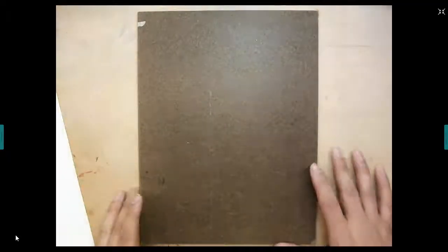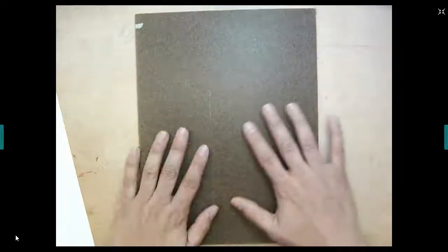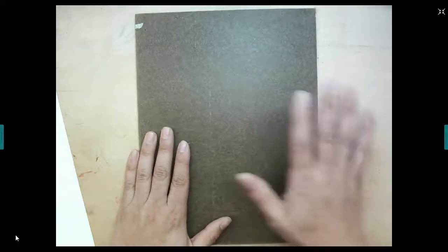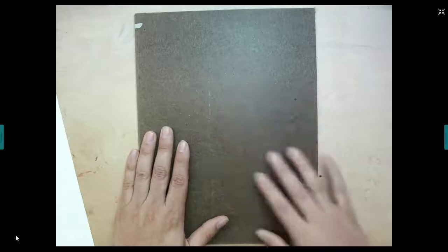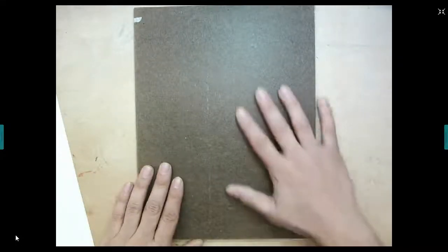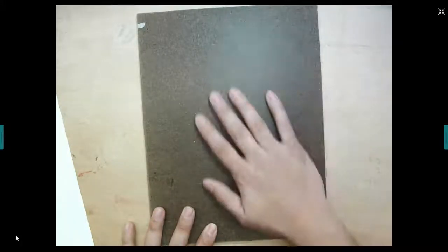Now, the Masonite drafting board should have a smooth surface. Make sure you're not attaching your paper to the rough side. Some of you may have a drafting board that has a smooth side and a rough side. Some of you might have one that has smooth on both sides. So double check. Make sure your drafting board, wherever you're going to put your paper, you put it on the smooth side. Okay?